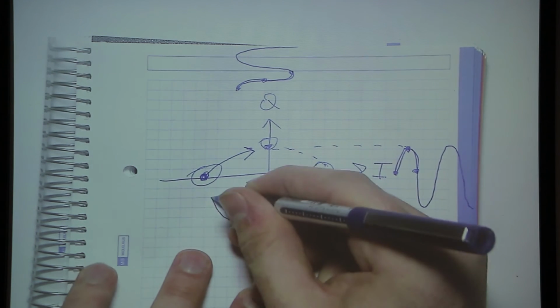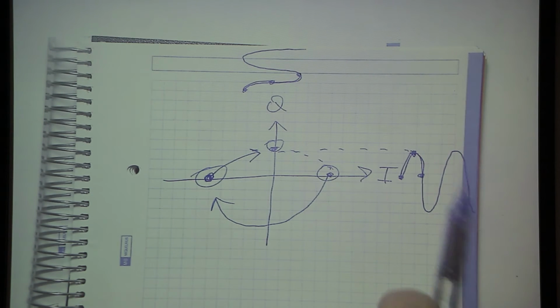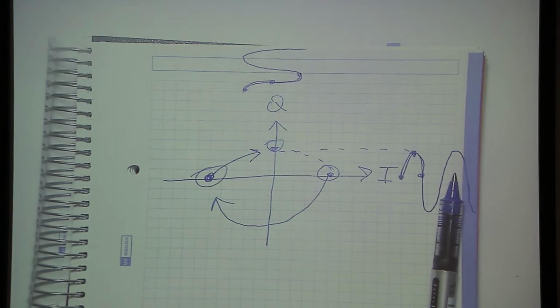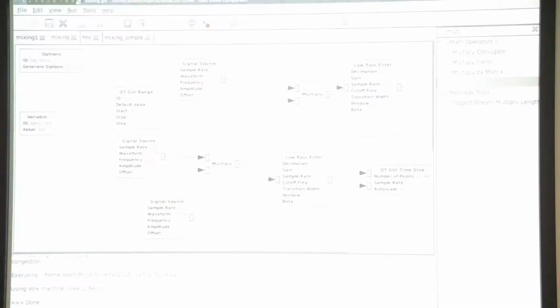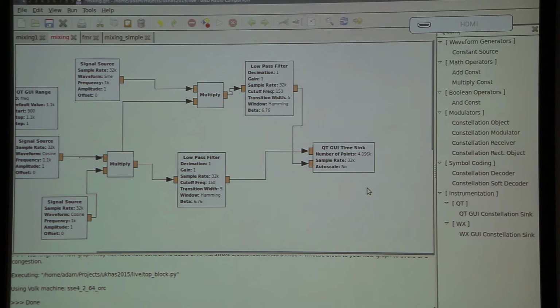and so on. What this means is if your input is some sine wave, then your point on this IQ diagram will be rotating round in a circle, and how fast it rotates round depends on the frequency. So if you're looking at some IQ plot with some points spinning round and round, that represents some sine wave coming in. And we can do that pretty easily in GNU Radio. So we'll take, I'll keep the time sync for now, and we can add what's...